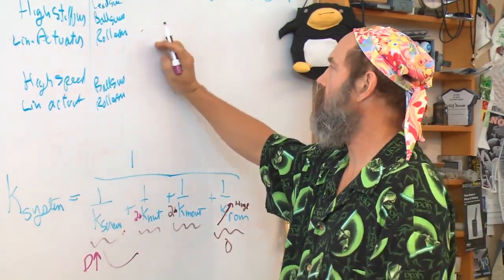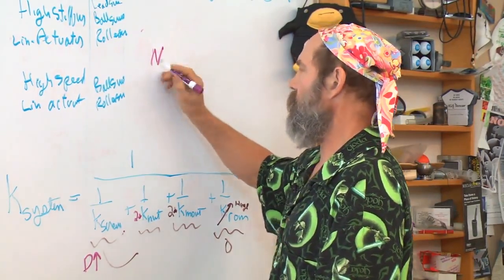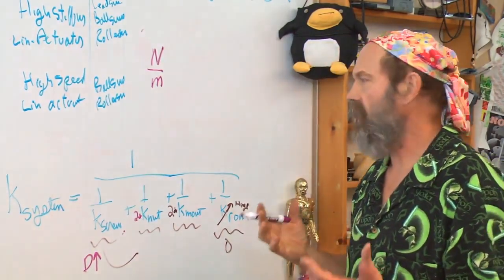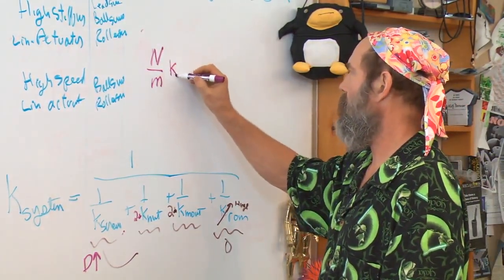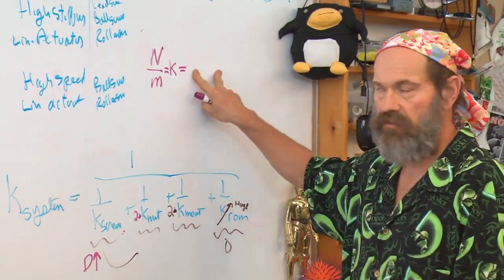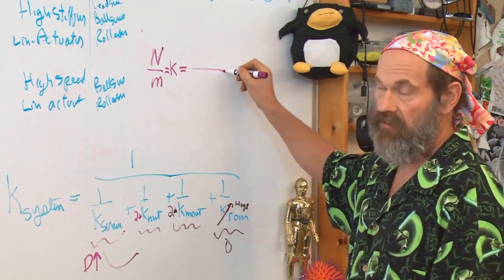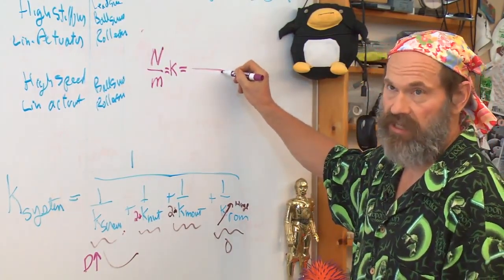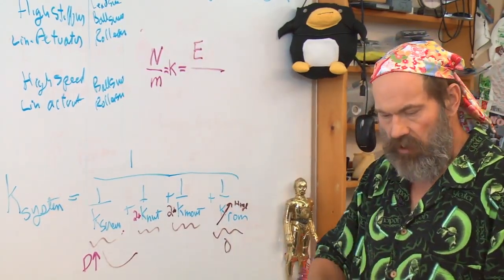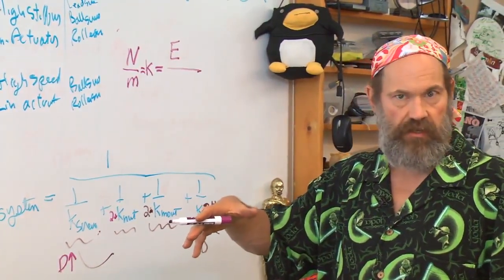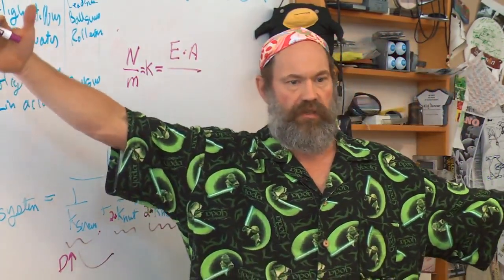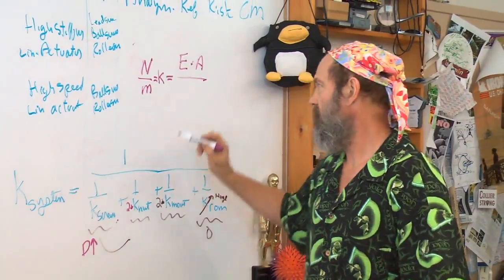What do you want to accomplish? Stiffness is newtons of force I push on, and I get some displacement, newtons per meter. And what makes sense? It makes sense that the modulus of elasticity of the material is involved, because the stiffness of a rubber screw is going to be a lot less than that of a steel screw. And the bigger the cross-sectional area is, the stiffer it should be. But the longer the shaft of the screw is, the more of a spring it is, so divided by L.